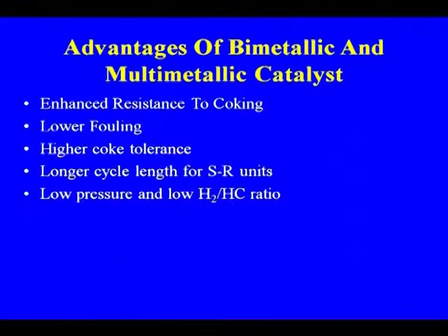What are the advantages? Why have we gone for the bimetallic or multimetallic catalyst? It enhances the resistance to coke. As I told you, the catalysts are now being developed so that they have more and more resistance towards coke and towards sulfur compounds, lower fouling, higher coke tolerance, longer cycle length for your reforming units, and low pressure and low hydrogen to hydrocarbon ratio, because if you are increasing hydrogen, then the operating cost also increases.